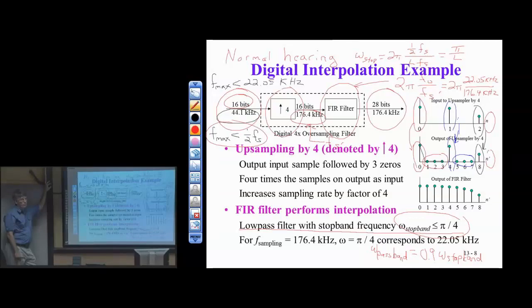Remember the 13.5 dB. It would be the averaging filter, but we can have FIR filters doing better than 13.5 dB. But 13.5 dB would give me basically 2 bits of quantization support. How many dB of stop band attenuation do I need for 16 bits? 6 dB per bit for one channel quantization. So it'd be 16 times 6, somewhere around 96 dB. That's incredible stop band attenuation. Pretty incredible. Okay, but with a long enough FIR filter, we could probably do it.